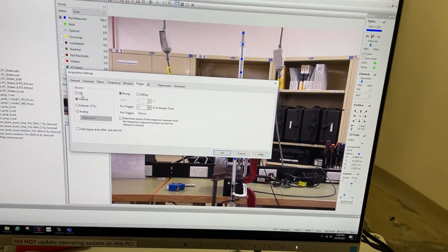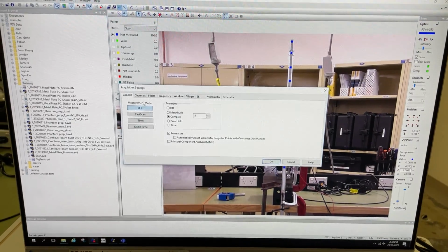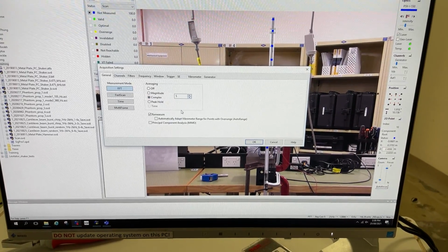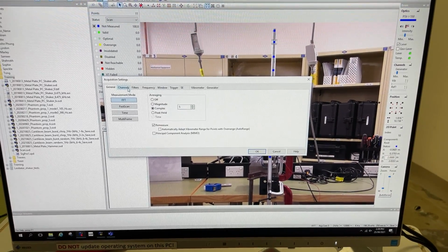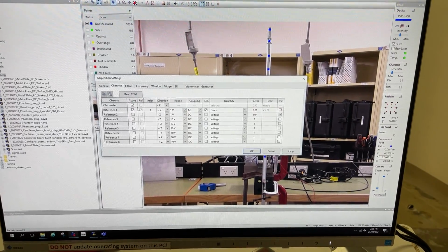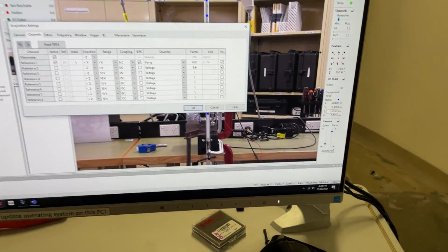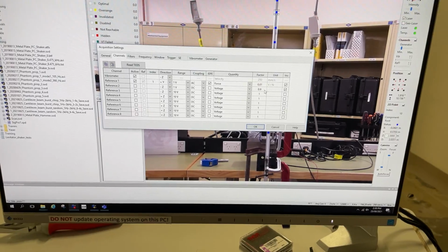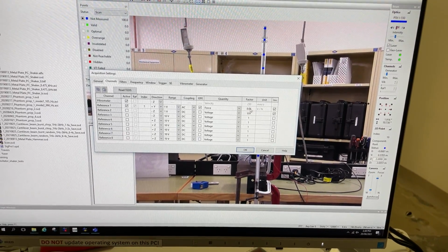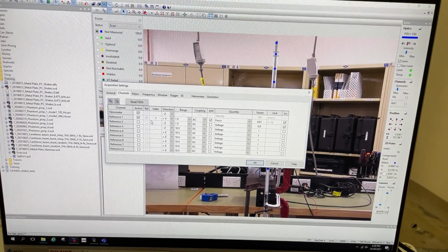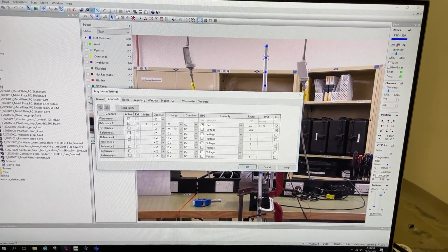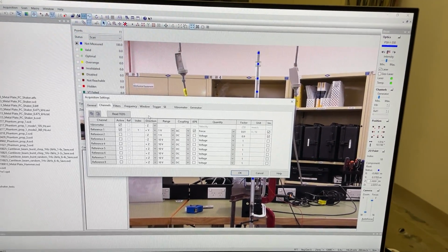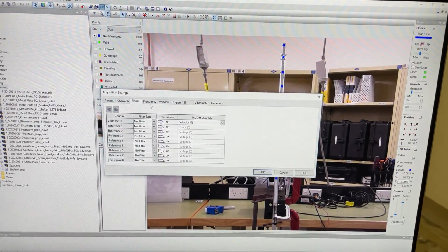In terms of the A to D acquisition settings, we're currently acquiring in fast Fourier transform mode. We're doing 5 complex averages per point. We can specify the vibrometer sensitivity, which is actually controlled from down here, 250 millimeters per second sensitivity, so we get calibrated units. We have the force transducer, which I showed, mounted to the shaker via the stinger with a range of 1 volt and a sensitivity of 10 millivolts per Newton. We have the option to turn on some filters, but we haven't specified them.